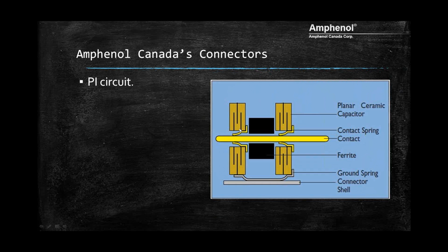Here is another sample, so you can see a better example showing you how the spring is contacted to the pin. One of the advantages of this system is that, unlike a solder joint connection, our contacts are removable. That's an important note for you engineers out there or people who are into reliability. If you have a problem with the contact, if the contact gets bent or damaged in any way, you have the ability to replace it.